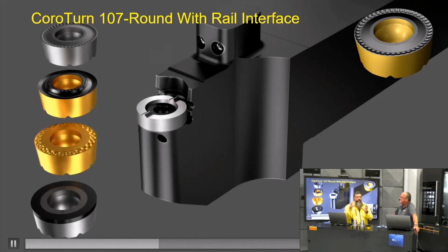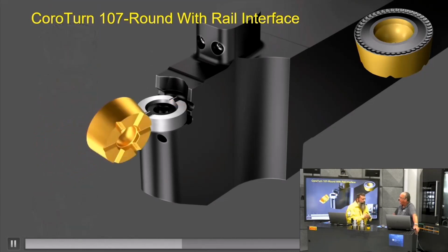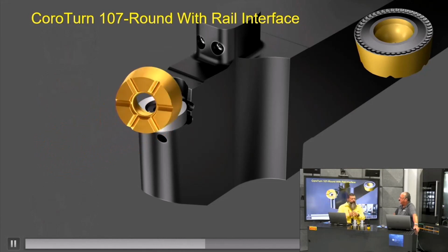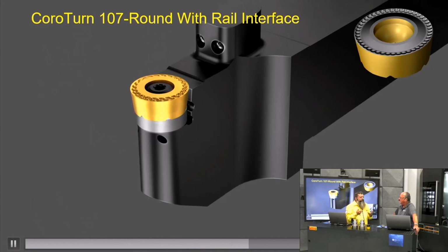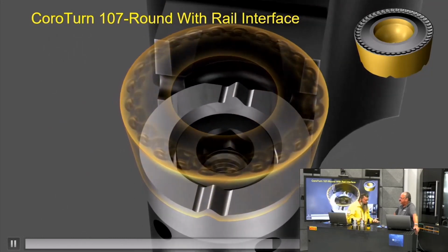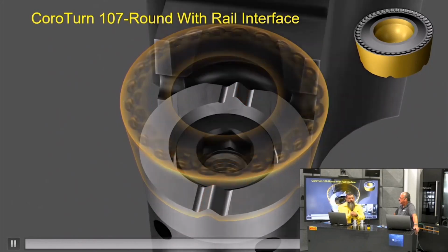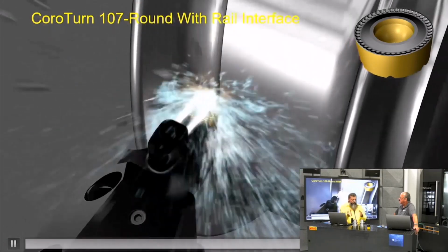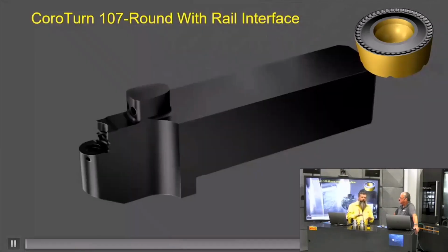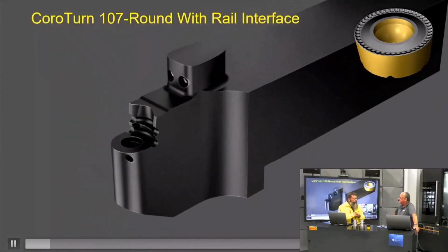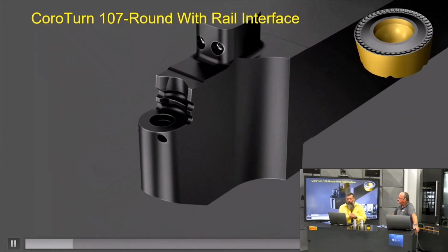Okay, big piece of feedback from the market, and I've heard it as many times as I care to mention. We don't like round inserts because we don't always get the use of all of our carbide. We don't know how far to index them. That's the beautiful thing about the CoreTurn 107. Indexes on the bottom, the slices, they match up, built-in indexability, built-in security, and no worries when it comes to a robust process if properly programmed.